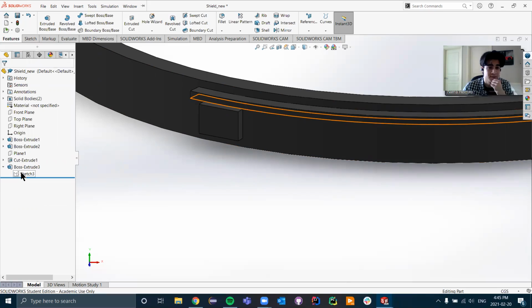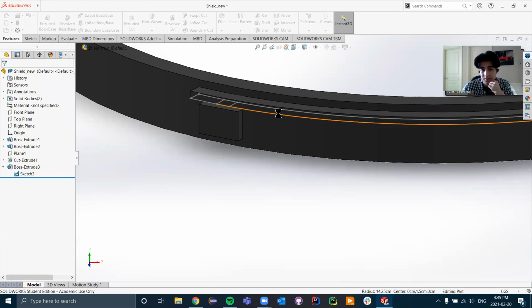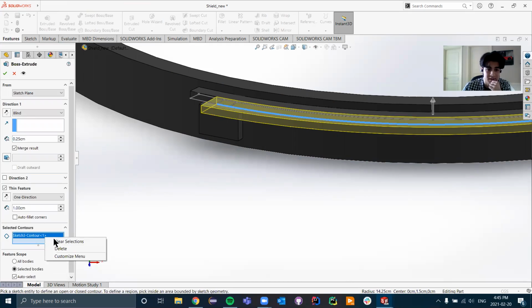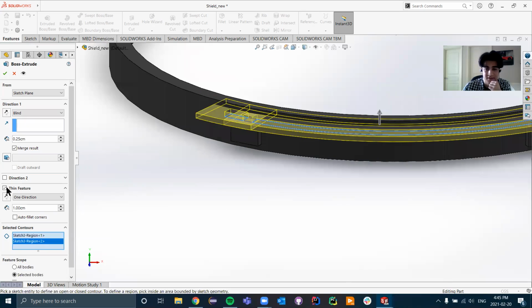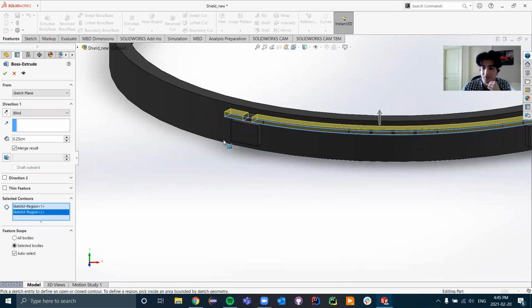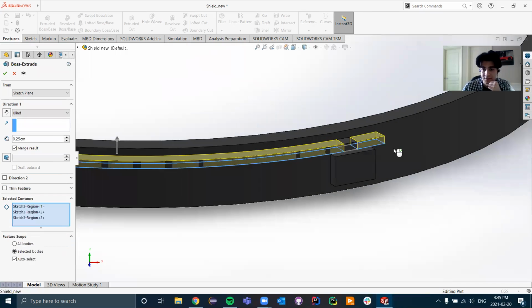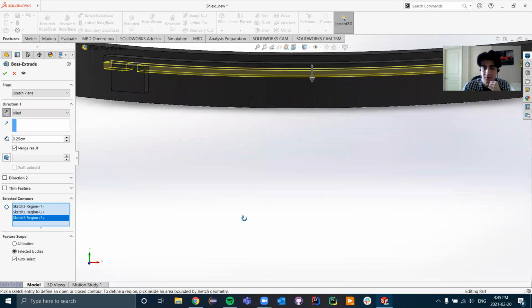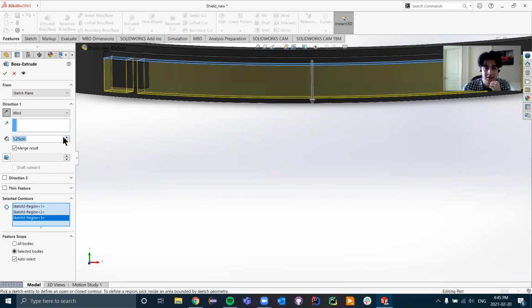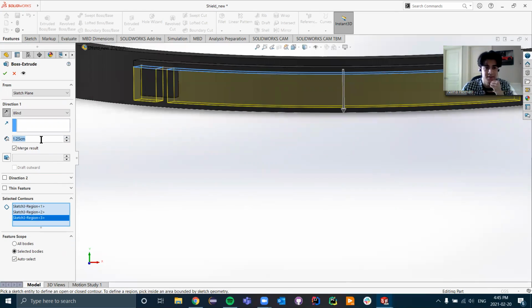And then what we want to do is we want to make our sketch visible once more and keep reusing this contour as much as possible. Now, if we click that contour once more, what we can do is we can actually get rid of this one and click all of the ones in between. And it's doing this weird shape because we had thin feature selected automatically, which is not what we want. And essentially, I'm going to change the direction of extrusion such that it goes underneath. And we'll just increase it by, I think this thickness was 0.75, if I'm not mistaken.